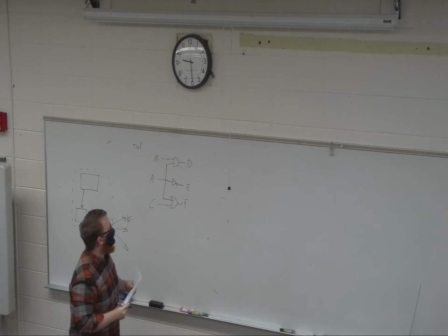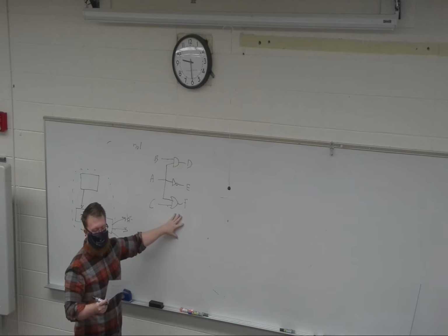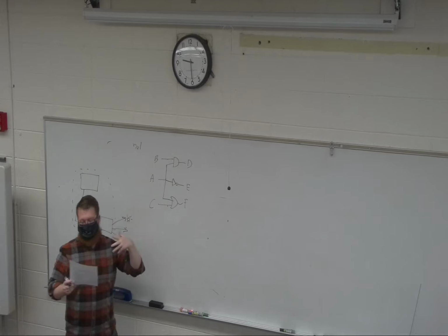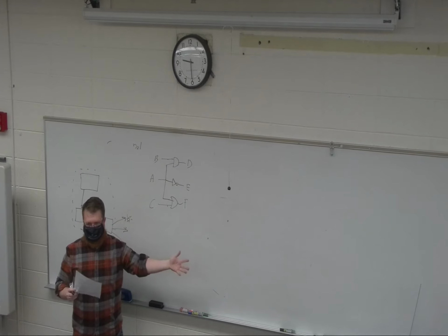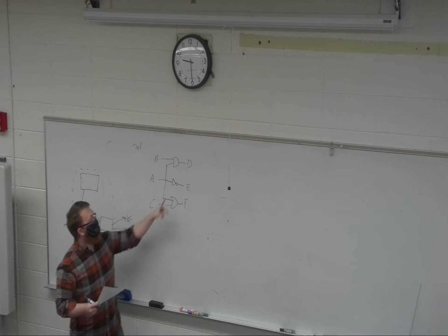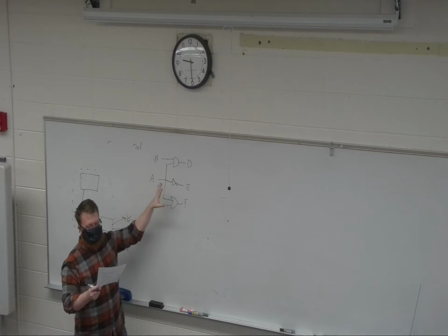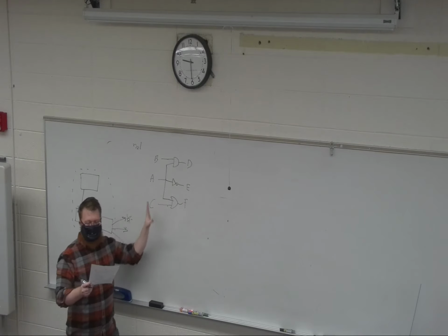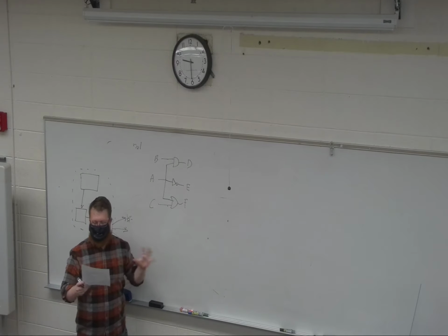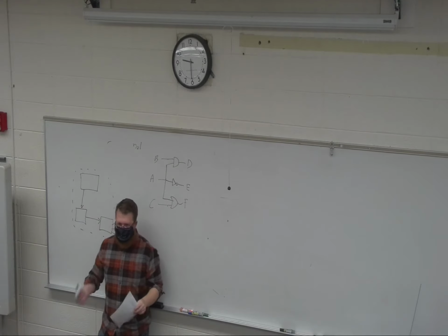Right, and then there's going to be a statement for each of these. D is equal to, E is equal to, F is equal to, and then it's going to go through that and it will execute after some amount of time. And in the book example, it uses D equals this after 2 nanoseconds, and E is equal to that after 1 nanosecond, and F is equal to its equation after 3 nanoseconds. So it's showing a different one. It does a poor job of explaining it's not synthesized that way.